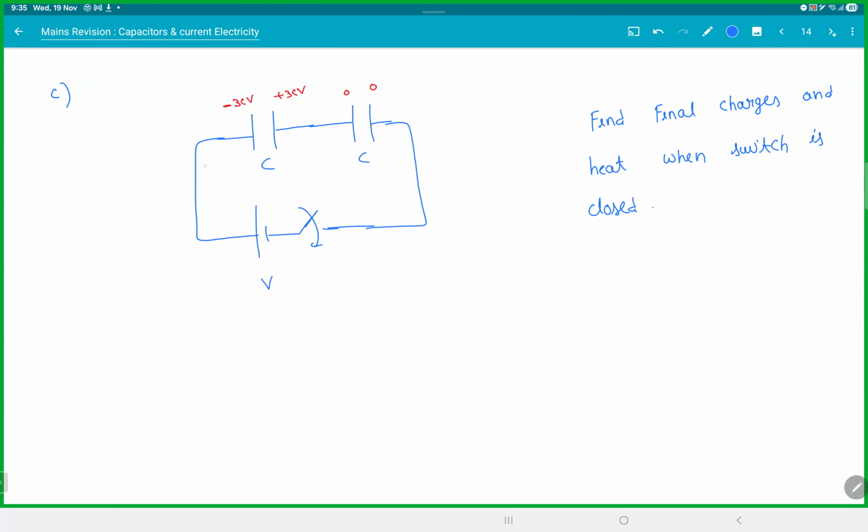Now, first thing, are these two capacitors in series? No, remember that's a blunder. Just because they're side by side, don't say they're in series. What was the definition of series? They should be in the same branch and have the same charge. Clear? Just because they're side by side, don't assume that. Only if they're empty, you can take that assumption. So then how do we handle this?